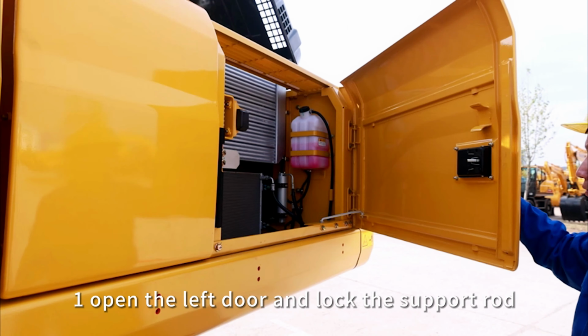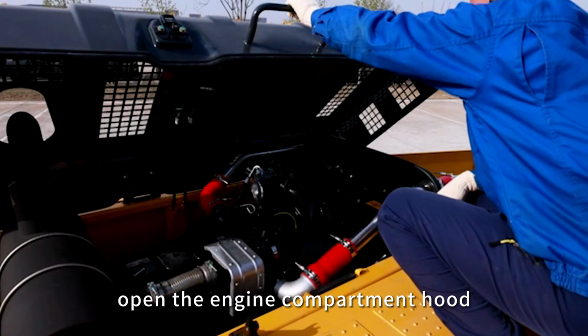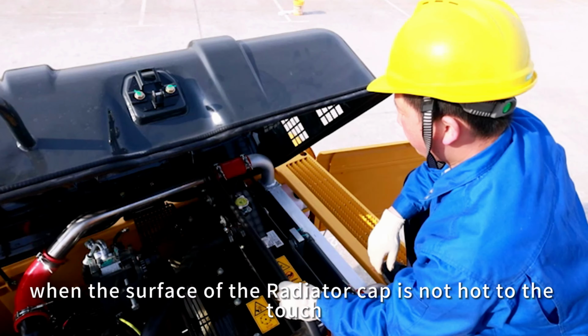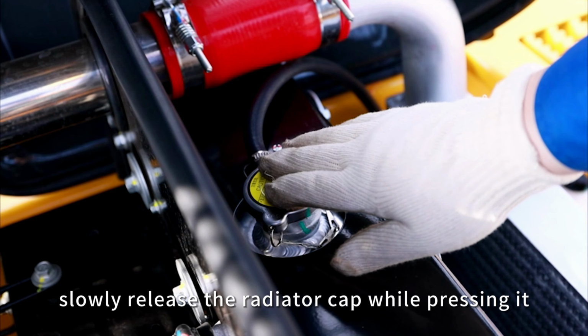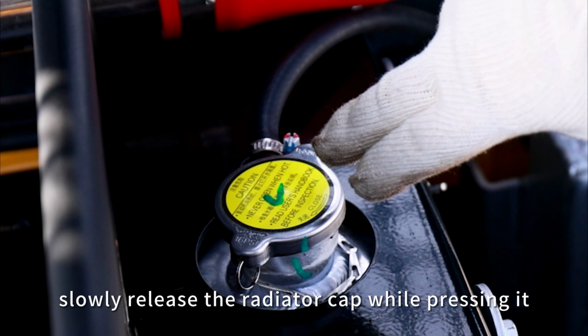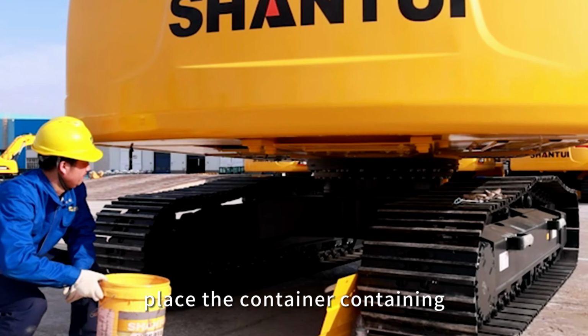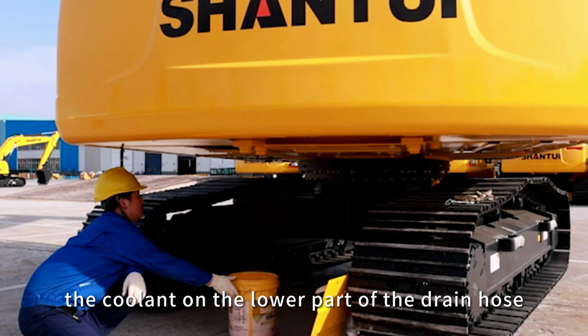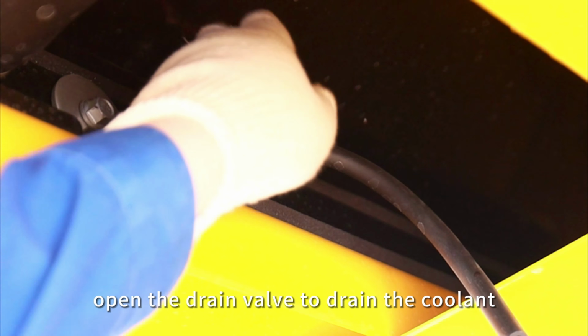3. When handling waste liquid, pay attention to environmental protection. Steps. 1. Open the left door and lock the support rod. Open the engine compartment hood. When the surface of the radiator cap is not hot to the touch, slowly release the radiator cap while pressing it, and remove the radiator cap. Place the container containing the coolant on the lower part of the drain hose installed on the drain valve. Open the drain valve to drain the coolant.